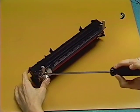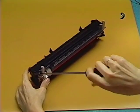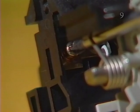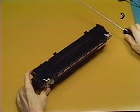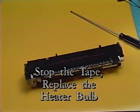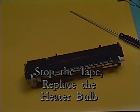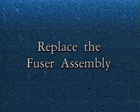Finally, replace the screw and washer that holds the heater bulb to the right connector holder. Stop the tape and replace the heater bulb. Replace the fuser assembly.